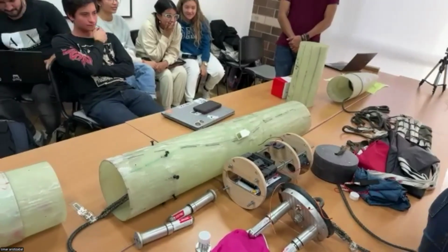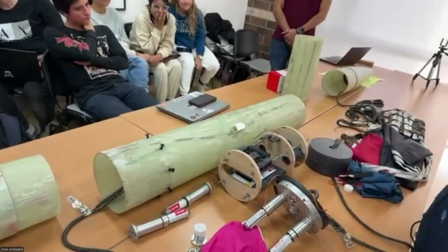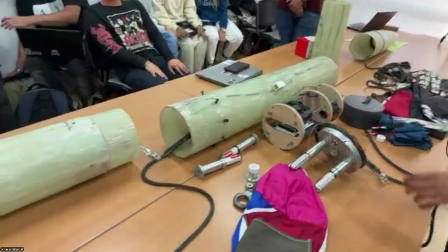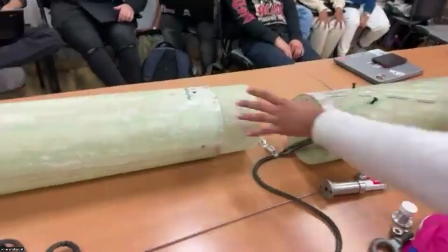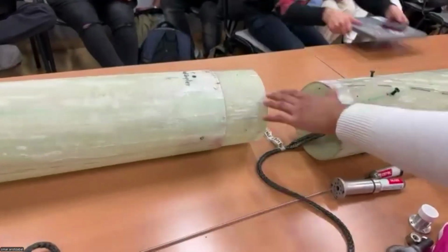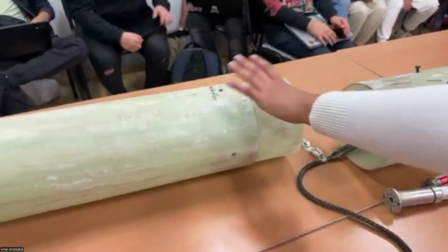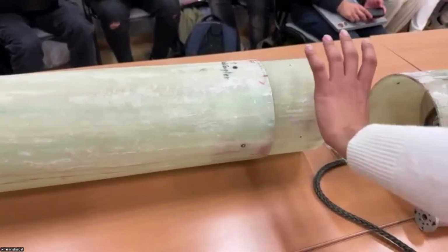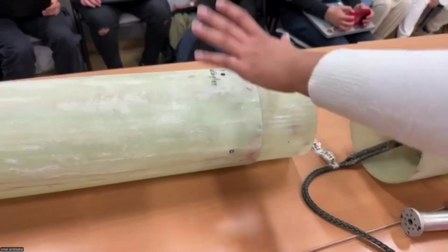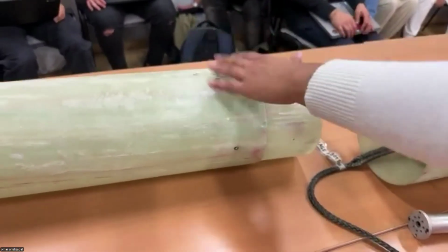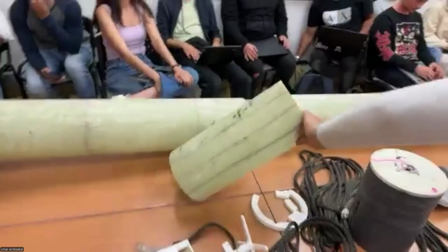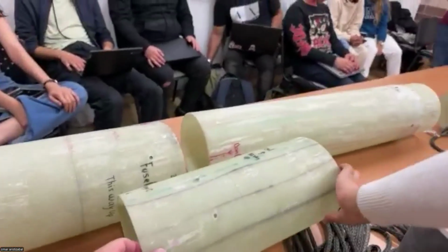So how long are your coupler tubes back to the body of the rocket? So this coupler tube, these two sections are not intended to separate, they are 18 centimeters long. It is slightly more than one caliber of the fuselage of the rocket, so it complies with ESRA requirements. And the other coupler, we have 2 in total. Well, 3 if we count the one on the nose cone, but we already talked about it.